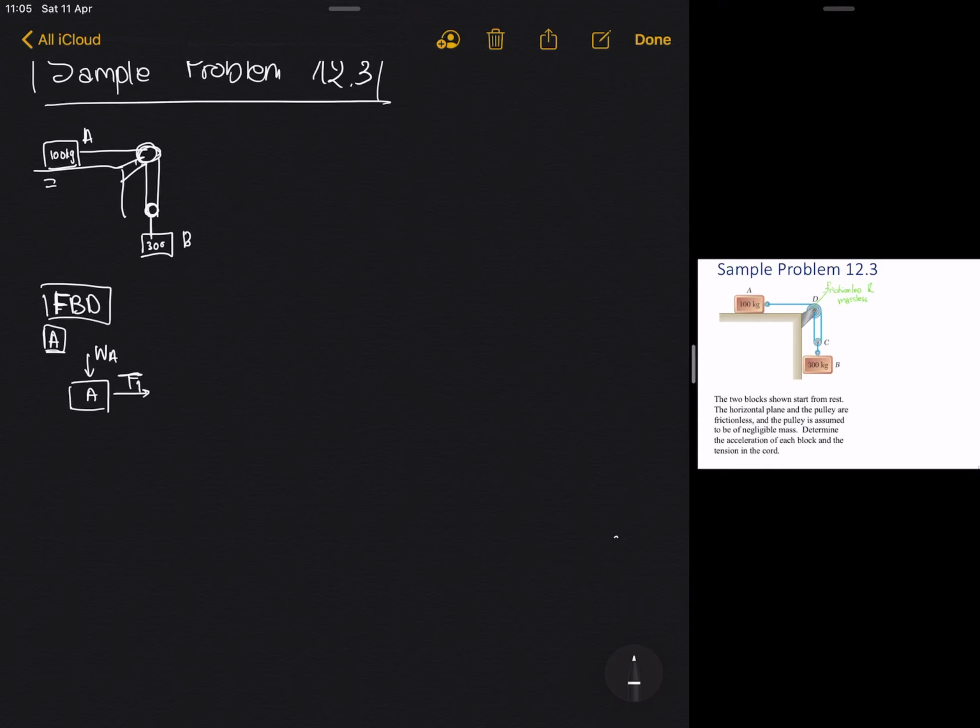First we draw the force. Secondly, we draw the coordinates. We have the coordinates. I would suggest do it like this: y and x. This is all. Okay. Then we have next also drawing the support force, reaction force. We have normal force here. And then we draw, of course, the angle or the dimension, but in this case we don't have it.